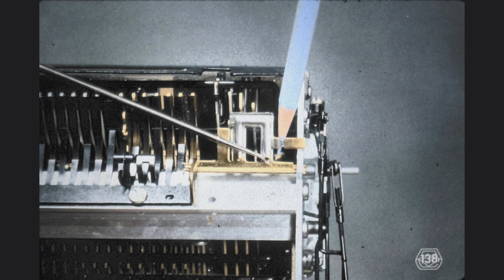Notice that the indicated spring holds the repeat stop plate rotated upwards. The action of the spring is limited by the lug, which partially covers the tip of the pencil. This lug rests against the bottom of the right side frame of the keyboard. By forming this lug, we should position the repeat stop plate so that it is in the way of the keylevers just as the interposer is released during single operations. In conclusion, notice that the space bar mechanism uses a separate lug on the repeat stop plate. It should be adjusted last.